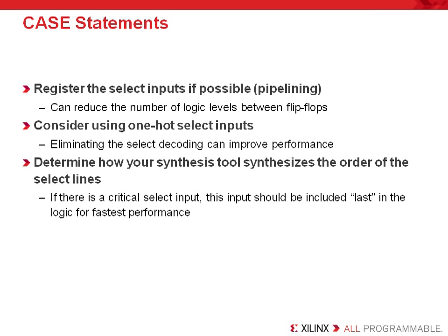Some other recommendations include registering the select inputs to your case statement. This is especially helpful if there are a large number of inputs to the multiplexer, since this component might require several logic levels to be constructed. Recall that the more logic levels in series, the more net delays in series, and this quickly adds up to a lot of delay. To work around this, registering the inputs to the select lines will effectively pipeline the large combinatorial path from the LUTs used to generate the select inputs.